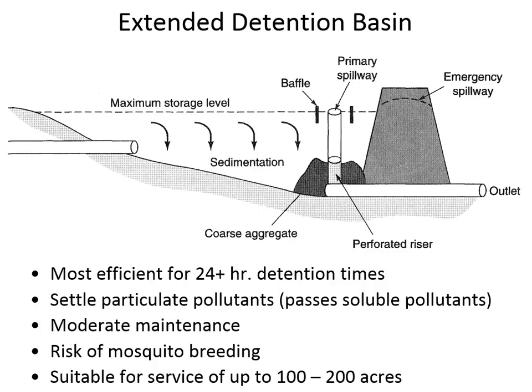Usually basins like this have the advantage of allowing particulate pollutants to settle into the bottom of the pond. And that's a good thing because it means they don't get into the stream. But then it's a bad thing because those particulates, if they're not removed from the pond periodically, are going to reduce the infiltration capacity of the pond.